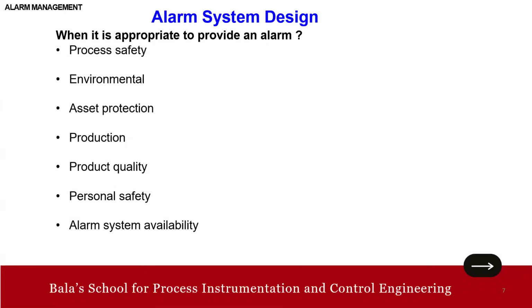Alarms are maybe proposed as a requirement during safety study, right? As it has layers of protection, LOPA, all these, right? However, these tend to look at issues in relative isolation. Relative isolation means it does not take into account wider consideration. Wider consideration means a separate review and rationalization to take place to confirm the proposed alarms are appropriate with feedback to the original study. Okay, that kind of brainstorming we need to take.